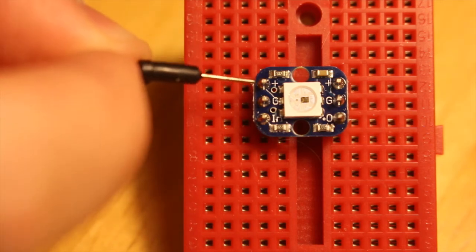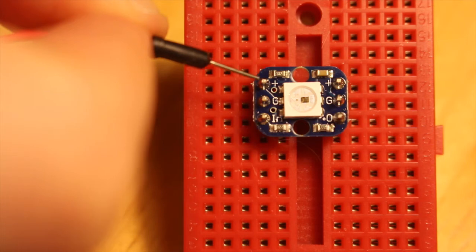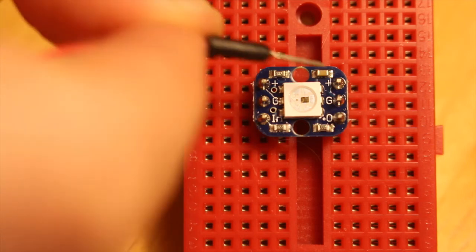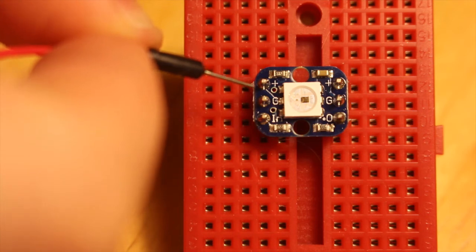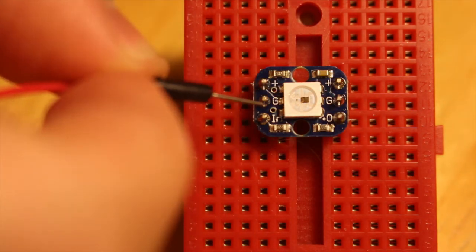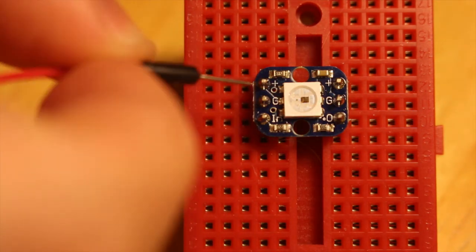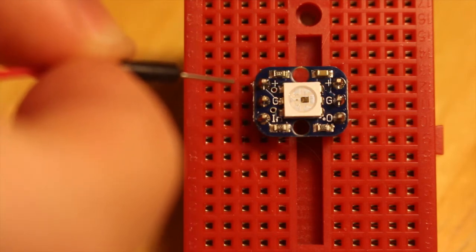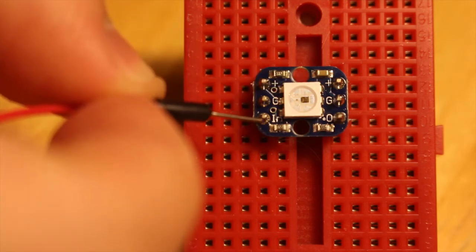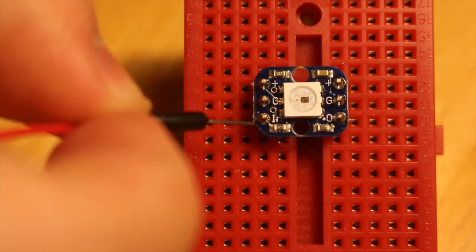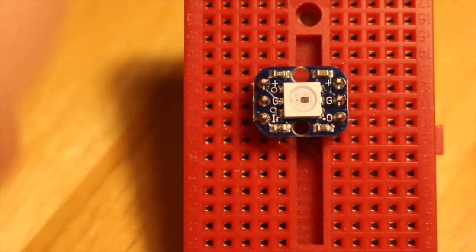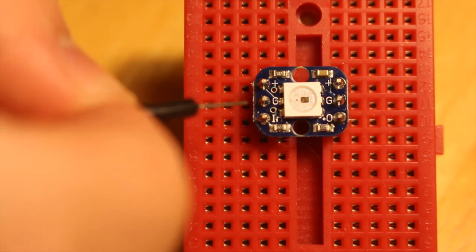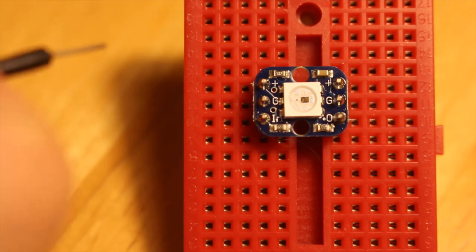So taking a close look at the LED, we can see that it's pretty easy to understand. Here you have on both sides a plus sign, which means we're going to connect them to the 5 volts coming out from the Arduino. The G pin on both sides means ground, so we're just going to connect them to the ground on Arduino. And you see there's an I and an O, which means there's an input and output. This way, for example, if we only want to connect one LED, we're going to connect this pin I to port number 6 on the Arduino.